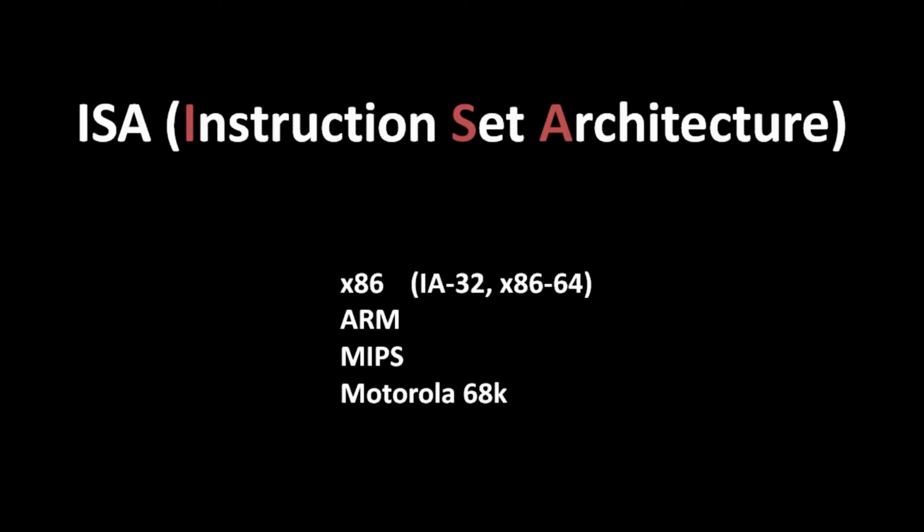An instruction set architecture tends to develop and grow over time. The x86 ISA, for instance, started in the 1970s, but has evolved since as Intel and AMD have released new processors. Their newer processors support the instructions of their older ones, and they have all the same registers, but they also support additional instructions and include additional registers. So x86 is more accurately an umbrella term that covers a family of continuously compatible ISAs.